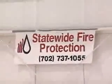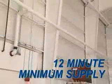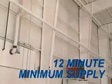Statewide Fire Protection recently installed an Ansul high-expansion foam system in the Imperial Air Hangar in Las Vegas, Nevada. The Imperial Air Hangar is a Group 1 facility measuring 42,000 square feet. According to NFPA 409, the supplementary high-expansion foam system has to fill the aircraft's storage and maintenance floor area to a level of 3 feet within 1 minute. The system also required a sufficient supply of foam solution to continuously operate the system for 12 minutes.